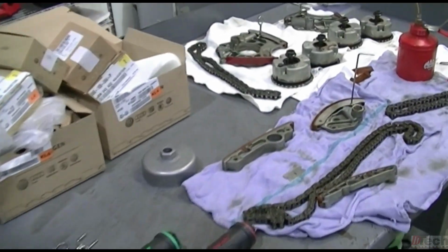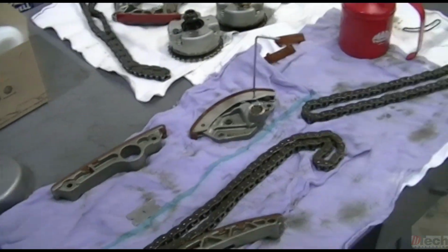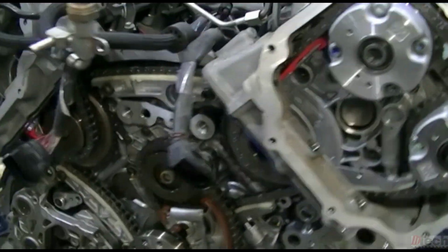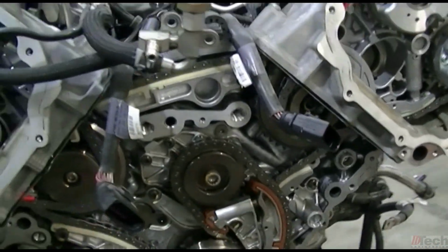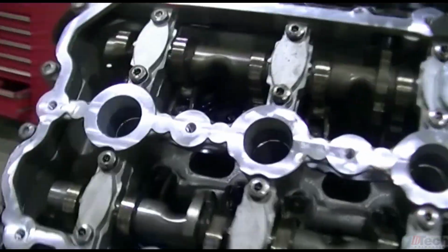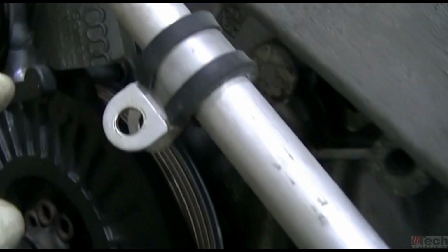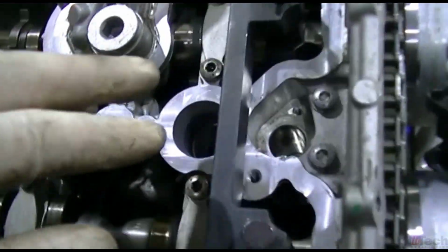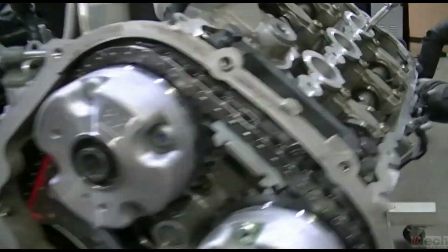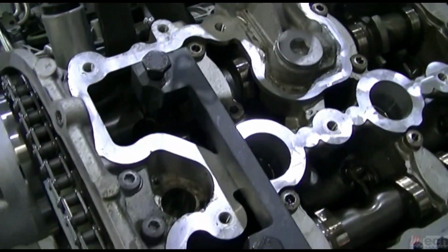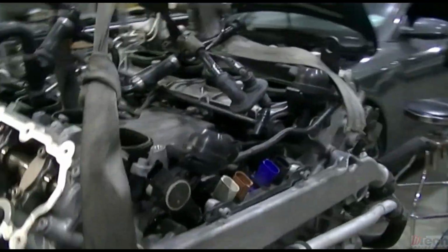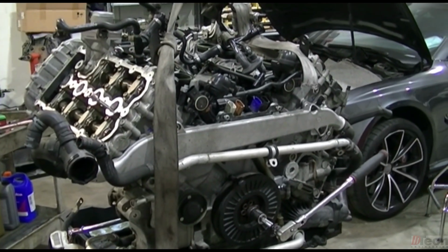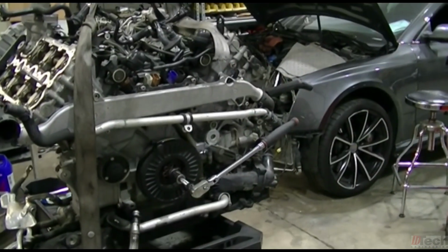Okay, so just a quick shot of all the components that got replaced, and everything in time and torqued. Tensioners have been released, and I spun it around already and locked it back in. And obviously this tool was already fitting before, and now you can see this one sits in there nice as well now. So both sides are now timed, and now just fun task of putting everything back together and installed back in the car.